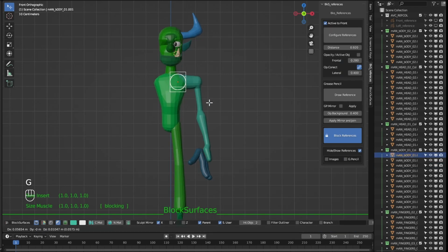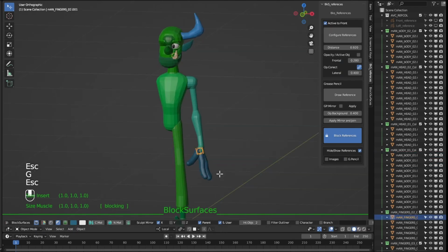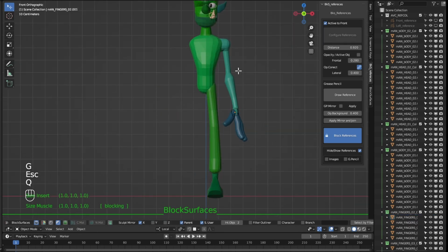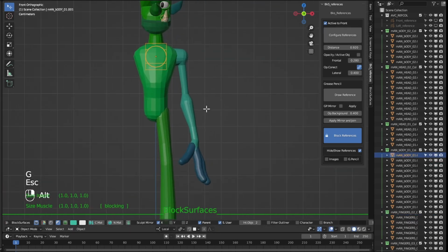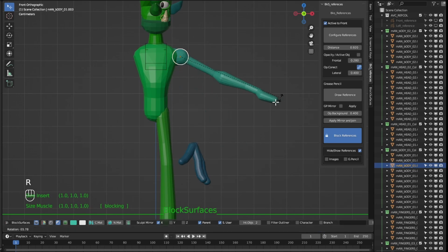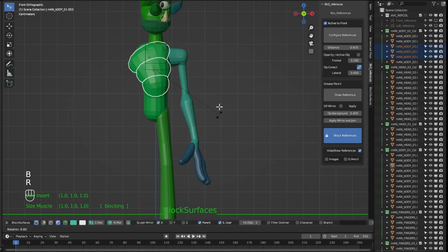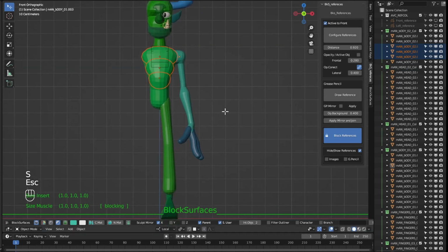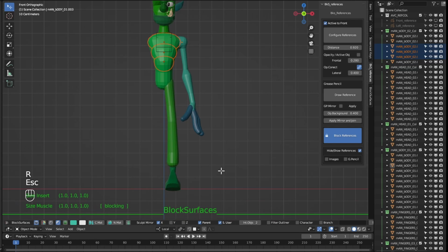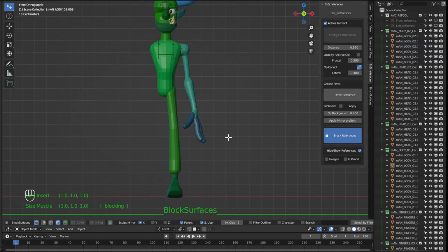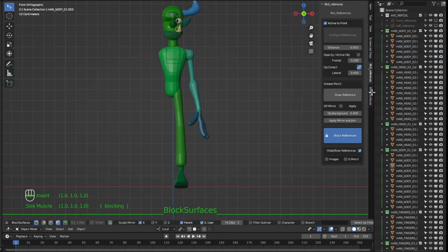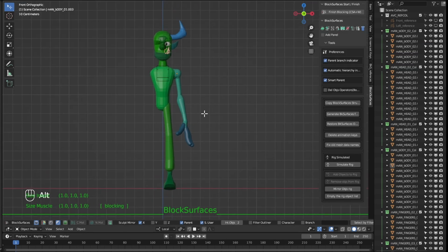Okay, so, from each branch, we have the parent object, which is the one that the rest of the objects in its branch follow. This allows us to have this hierarchy in the branches. We can use these hierarchies that the branches have to adjust them, change proportions, pose the character, etc. Now, let's see how we can relate the branches to each other. With hierarchy between the branches as well as between their objects, we can make the rest of the branches move when moving the trunk, or move the fingers when moving the arm.